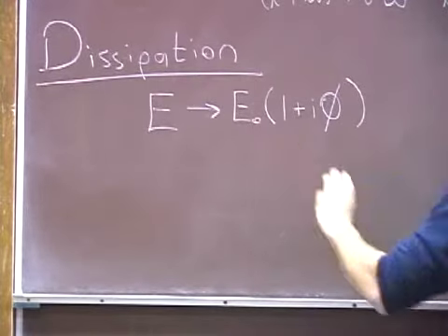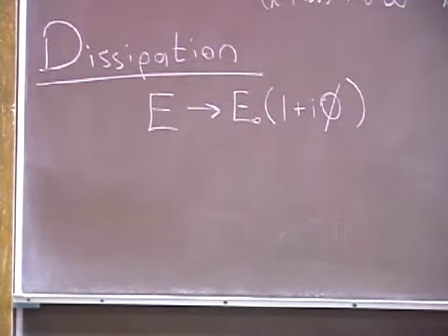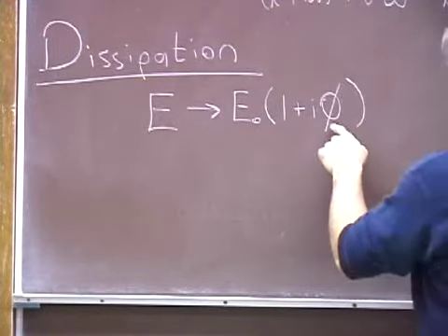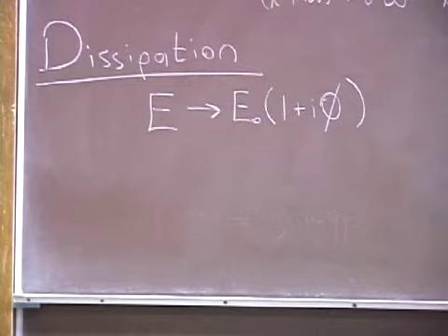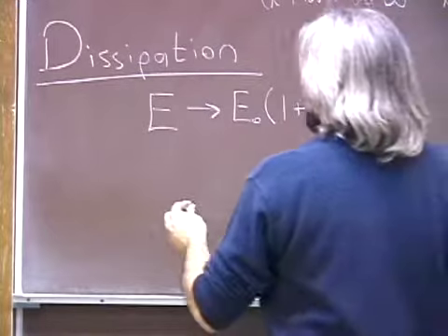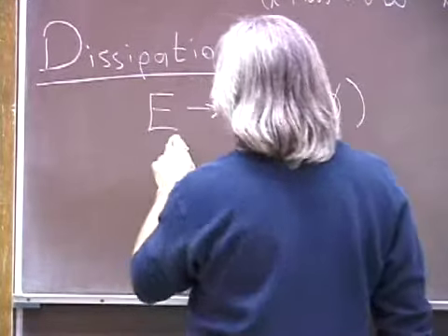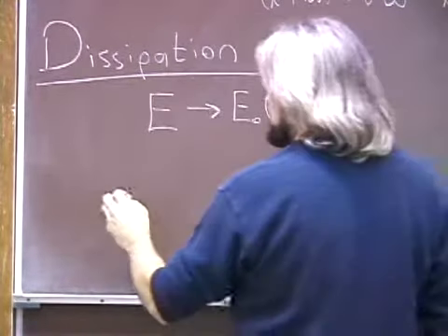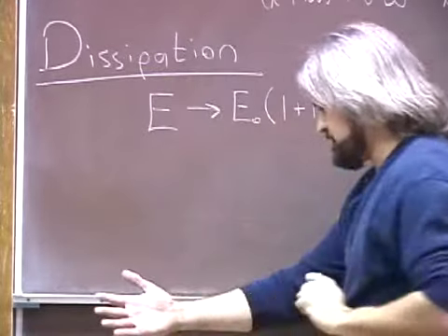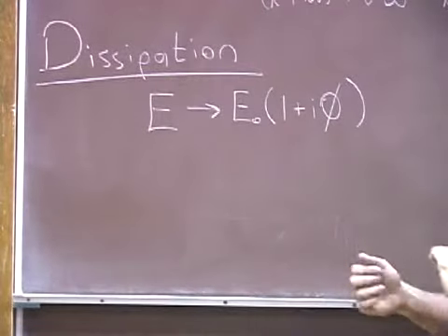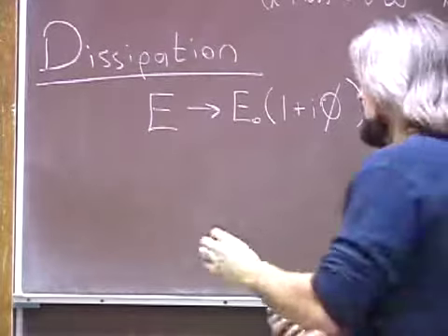The real part of the Young's modulus is what we would typically call the elasticity. The imaginary part of the Young's modulus is what we would typically call the dissipation. And I'll explain why that is. If you want to know the dissipation in some sort of physical system, it's very easy. Take that system, apply some cyclic stress to it. One cycle.